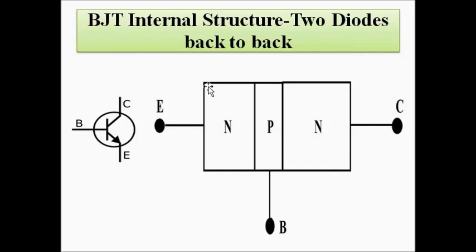analysis. So if you pay attention to only this much of the portion, you will see that it consists of an n-type block followed by a p-type block, which is the emitter and the base. So this emitter base block combined together, do not think about the other one, just consider these 2 blocks. It can be viewed as a PN junction diode, isn't it? These 2 blocks, emitter and base, form a PN junction diode block. You can visualize it in that way.